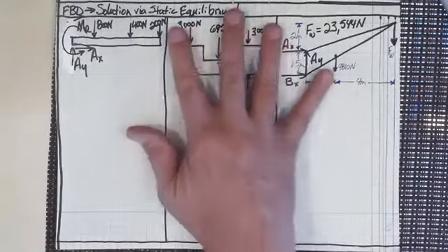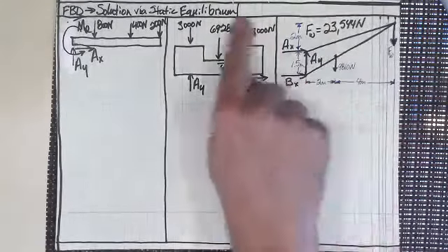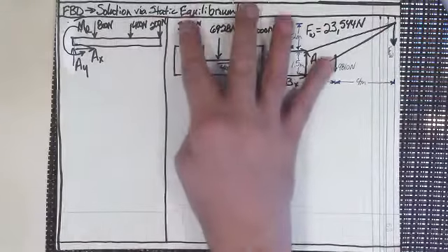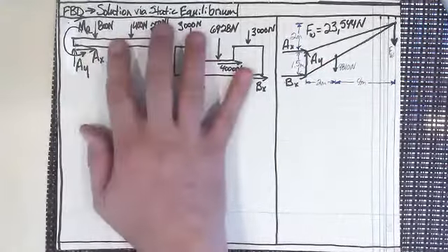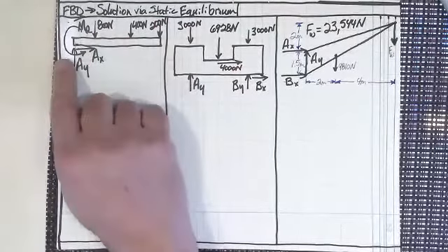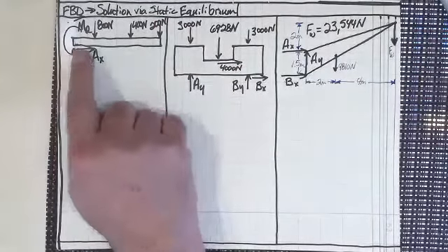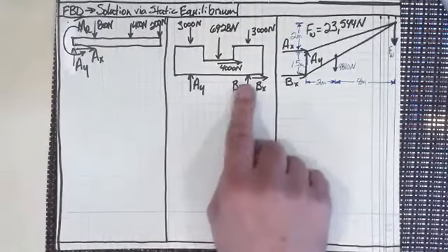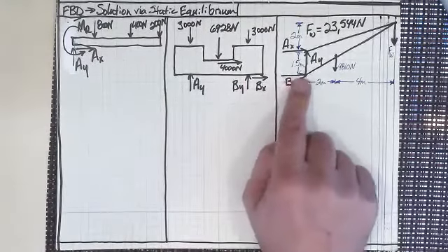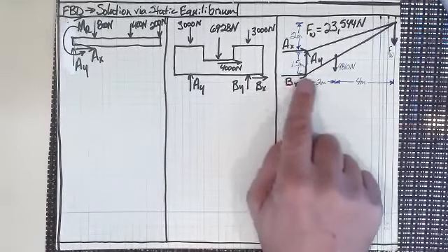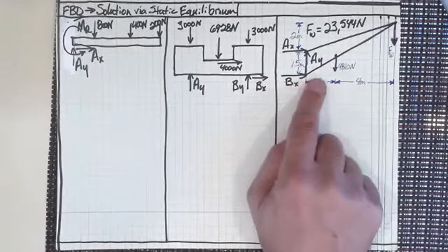And what I did was I've now expanded, since we went in the last lecture from the pictures to the free body diagrams, and we've seen what the reactive forces are that should go at various different support locations, right? This was a rocker, so it only stopped forces in the X direction.